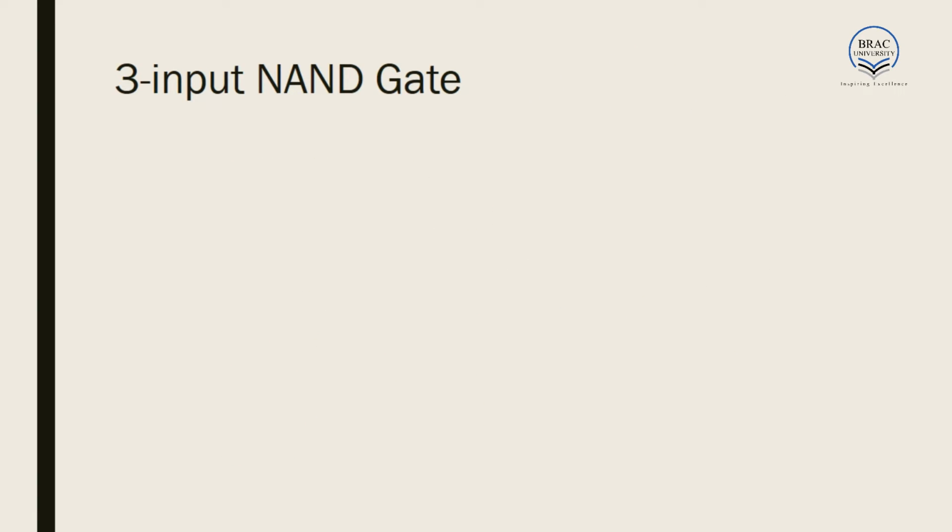Now we want to design a NAND gate or any other gates. We want the case of ideal inverters, that is, the inverter which will have two times the width of PMOS than NMOS, to get a similar type of result. Now it is not really easy: if we increase the width twice, all the circuits will not give the same results as the inverter. Why is it not so? Let us look at the NAND gate design.